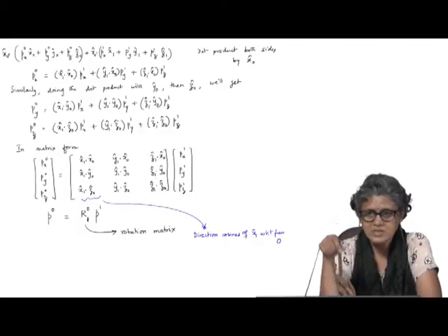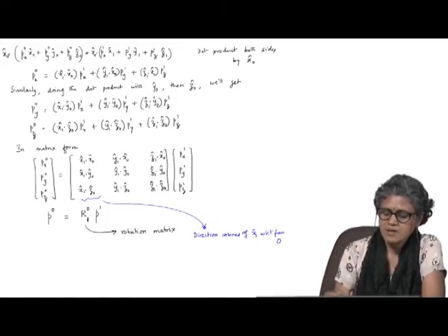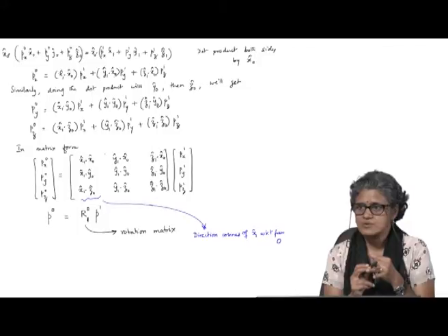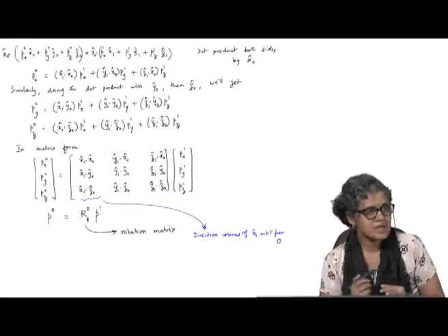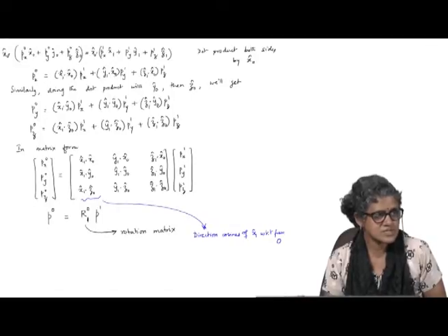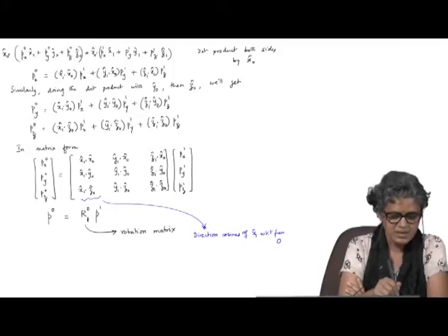You have only 3. The axes are coincident, the origins are coincident. You only have 3 independent quantities, and that is because you already have that x1, y1, z1 are orthogonal, you know that, right. So, that gives you three relations. In addition, you have for each column, the sum of the squares of the direction cosines equal to 1. Okay. So, it is only 3 independent quantities that you have in this matrix.